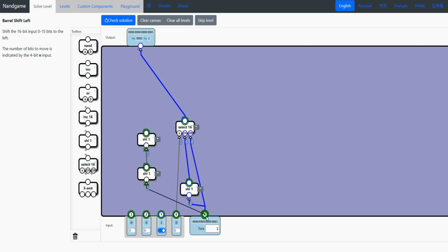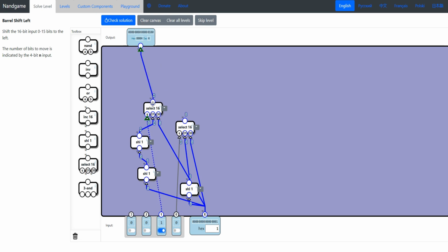And let's for now hook it directly up to X. And again, hook our select to this flag here. Hook up the shift left scenario to D1. It'll go if that flag is on. And our D0 again directly to X, just for now. So let's disconnect this one here and connect up our shift left. So there we go. We can see if it's on, it shifts left by 2.